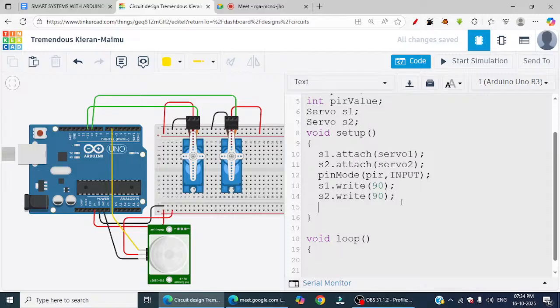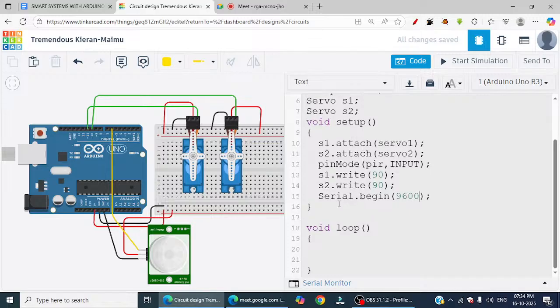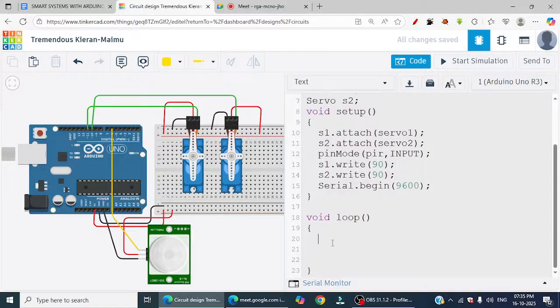To use the serial monitor, we know that we should use a function Serial. If you notice, in Serial the S is capital. So in the syntax, like we did lcd dot begin 16 comma 2, here we need to do Serial dot begin, and the speed of your Arduino board, it is 9600. It is called a baud rate. We call this a baud rate, 9600. And inside void loop, am I going at the correct speed? If I'm going a little fast, you can ask me to wait.